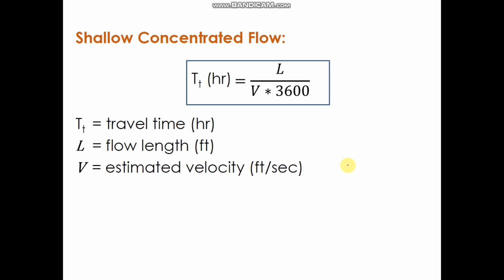So this can be very much applicable in the calculation of storm runoff from a land parcel for development. When we have to calculate the storm runoff for a land parcel which is less than 5 acre or 10 acre where the development has to happen, there will be partly sheet flow up to 150 feet.